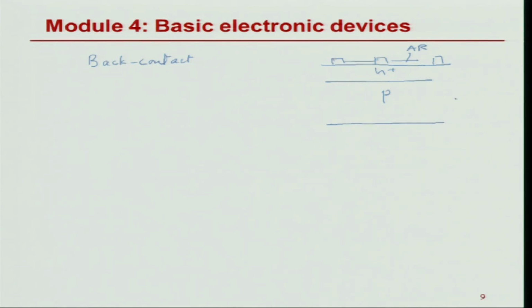On the back side, now I repeat this process, but not for n plus, but to get the p plus. And for that I can use gases like boron bromide or even diborane. Those can be used to oxidize the surface and introduce additional p-type doping. And finally, I will use silver aluminum paste for making the back contact.